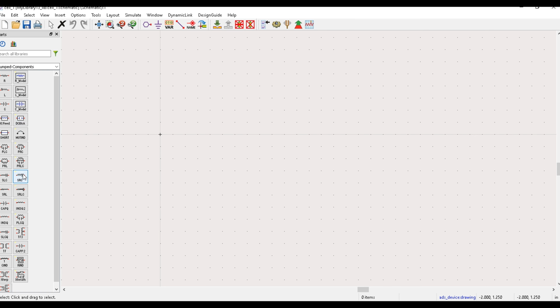So the data display window, when you first run it, a blank display is shown. What we need to do now is select our rectangular plot here. Click on it. You place it anywhere on the display window. Then for this particular design, we want to plot two parameters, the S11 and S21. So when you click on the S11, you first click add, and we want our result in dB. So make sure the dB is selected and click OK. If we click OK here, you see our plot for the S11.